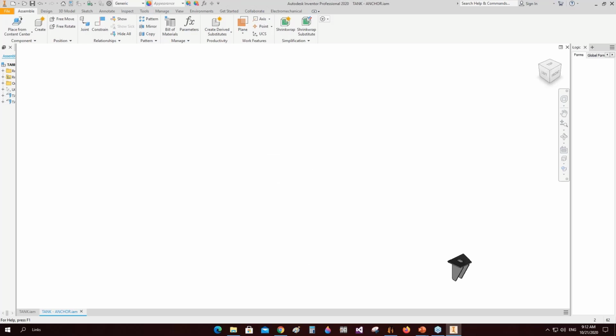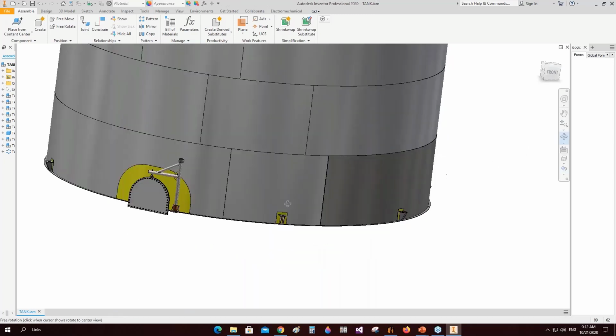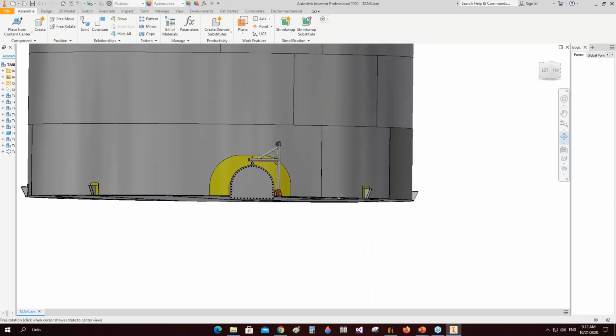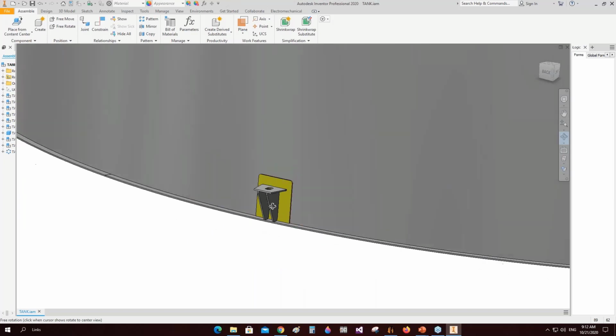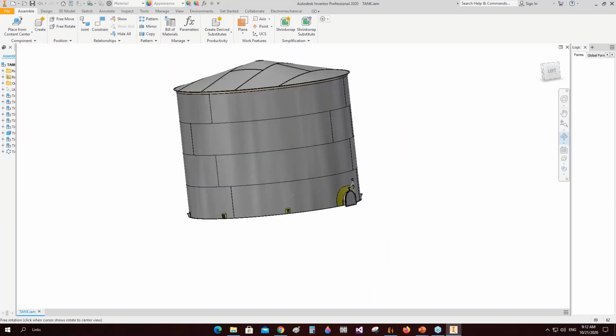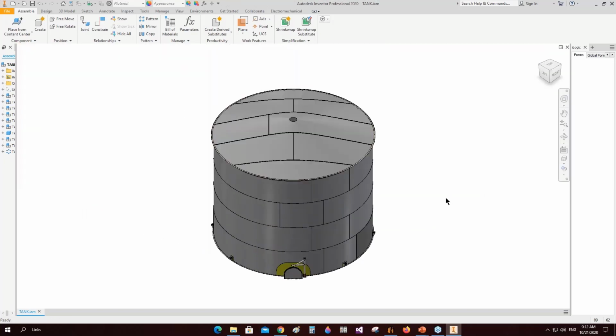After that, it will be added to the model and the pattern. Okay, a circular pattern for this one around the tank. And easily you can detect if you have any clash or something like that. So you can decide if you want to rotate or change the orientation, change the number of the anchor bolts around the tank or not. I think now we cover all points in this session. And if you have any questions, you can go ahead.